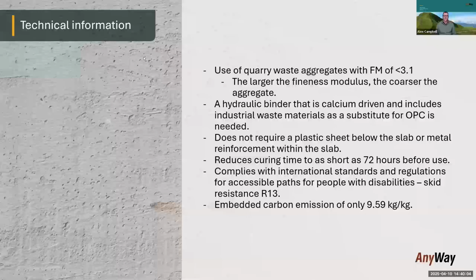As far as international standards, what we're looking at is strength, durability, and skid resistance. We are complying with skid resistance and strength for use in sidewalks and in slabs. And we're also looking to reduce the embedded carbon emissions, right? So we're reducing it significantly compared to using an OPC or OPC slag or OPC pozzolanic blend of that same thickness or for that same application.